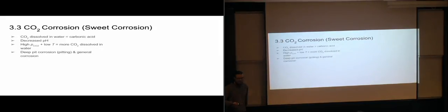And that sometimes happens in a subsea system where you get cold temperatures, especially if you have pipelines going quite far along the seabed. So you get approximately 4 degrees Celsius as the environmental temperature around it. So it's fairly cold, and then you also get a fairly high pressure. So that's going to create an even more acidic flow.